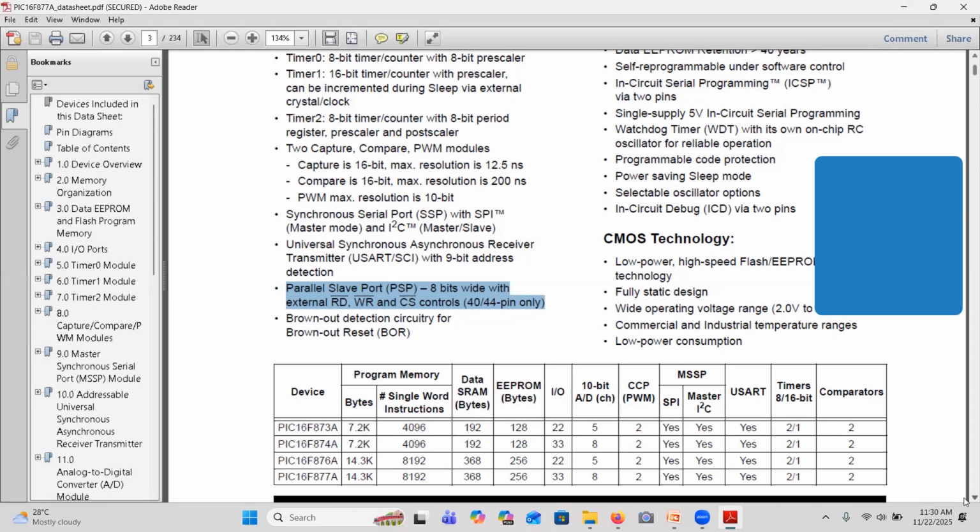Yeah, each one of these circuitries can be used for a different purpose. It is not like we have to use all of them to work with this microcontroller. We won't use I2C in our project right now. So we will use SPI, SCI, but we won't use I2C. We will use the parallel slave port to interface a display. So these peripherals are available ready-made in that microcontroller. Whether it is applicable to your project or not is based on your project nature. So the embedded architect, the product architect, will decide whether we are going to use that or not.